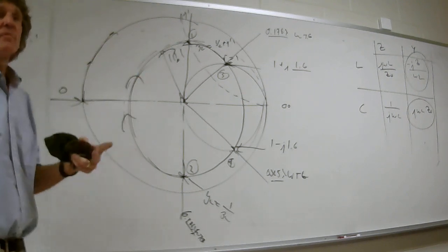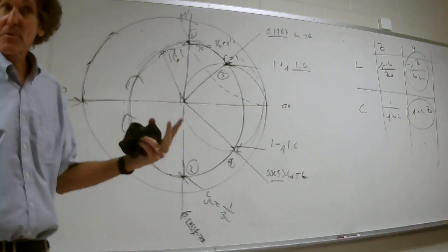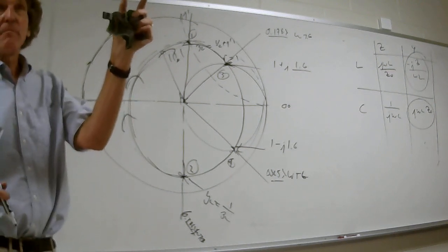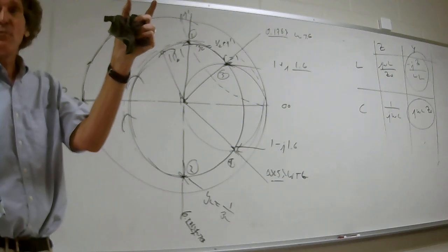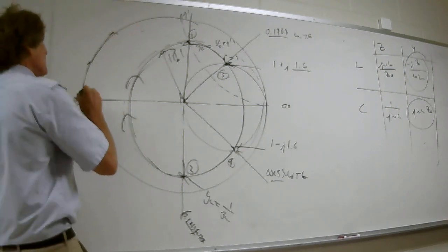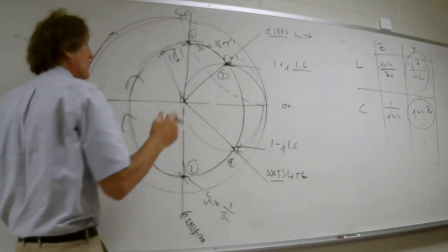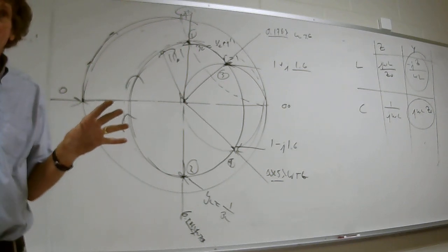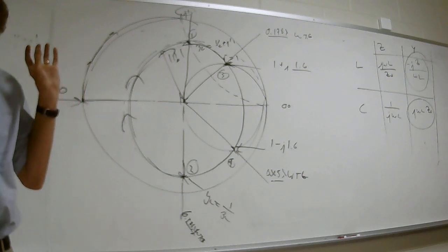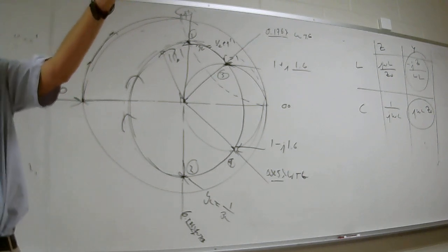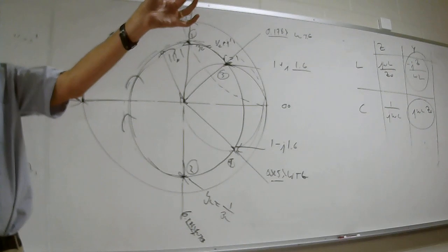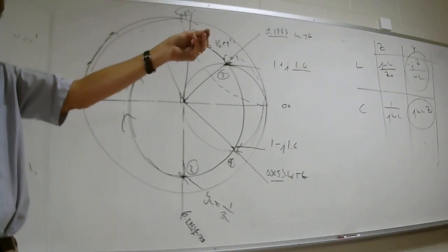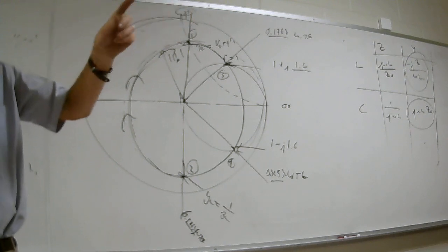If you want a normalized impedance, remember, we're using the transmission line. Say we've got a plus or a minus j something. Minus j1, we want to get rid of it. We move from here to here. Here's plus j1. It's exactly 1/4 of that circle, or lambda over 8. Do you all follow me? Take that and stick it in series. Can you all understand that? I'm replacing that element that was an inductor with a transmission line in series.